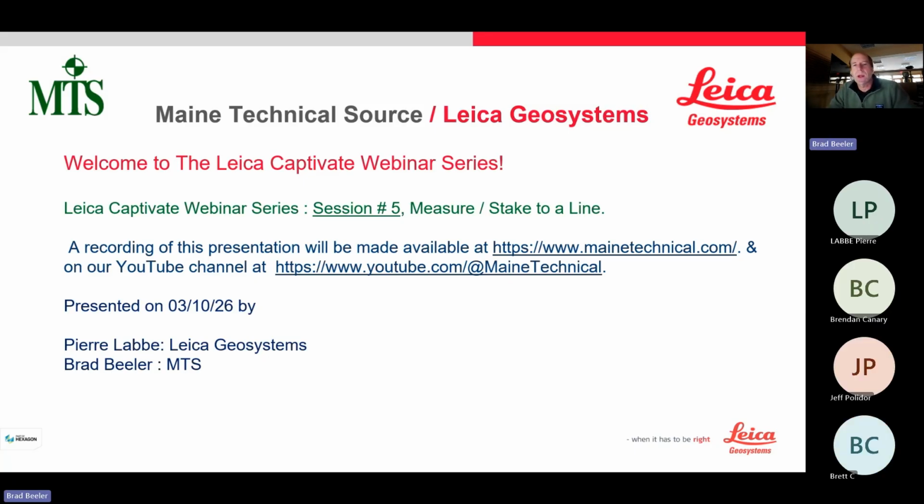Quickly, the difference: we're going to be covering two apps, but they're bundled together. The difference between the two apps is this: the Stake to Align app is a layout tool used to guide the user to a specific design position, station and offset, relative to a line. The Measure to Align tool is a reporting tool that computes and displays the station offset of your current position relative to a line. So one of them tells you how to get to a point on the line. The other one tells you where you are with respect to a line. But Pierre will go deeper into this, but that's the basics of it.